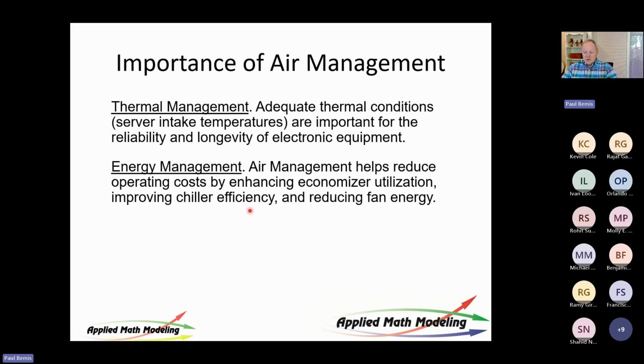Chillers, the efficiency of a chiller: if you return the hotter temperature, so you want a really hot temp coming back to the chiller to be dumped to the atmosphere. That's what chillers do. They pump heat into the atmosphere. And in general, for every degree C or centigrade that you increase the return air temp, you'll get about 1% performance improvement in the efficiency of that device. That's a very coarse rule of thumb and does not take into account economizers and other things. So it will be at least that. So the idea is efficiency.